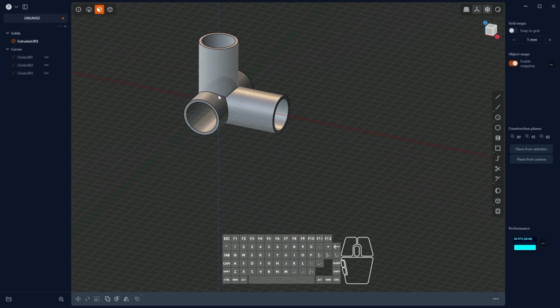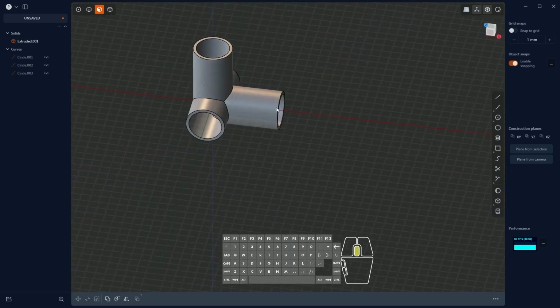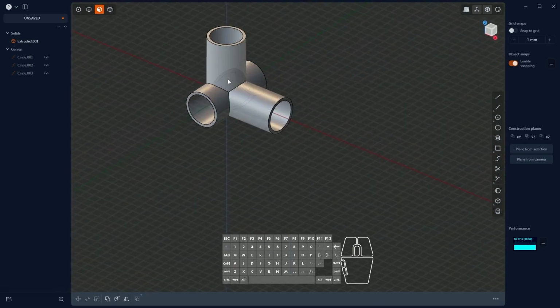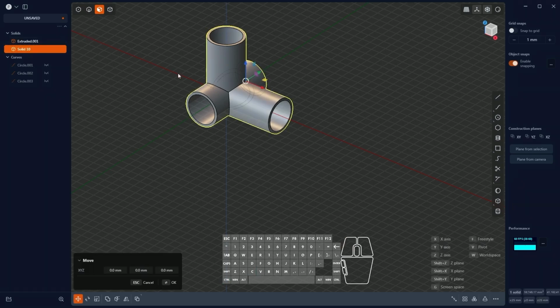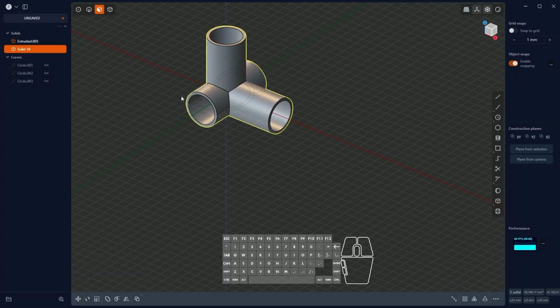At this point, this solid is a single solid, and if you would like to achieve something like this, we can end here. But also based on this solid, we can create three separate solids, so that, for example, it is easier to make such a part. I will add a copy of this solid, Ctrl+C, then Ctrl+V in the same place. Here I will not move anything. I will turn off the visibility of the source solid. And now, based on this solid, I will create separate solids.